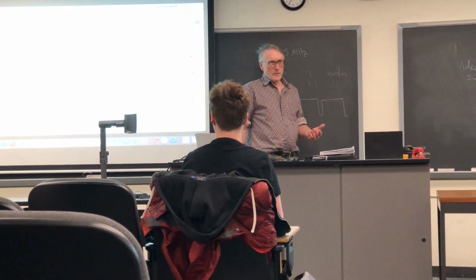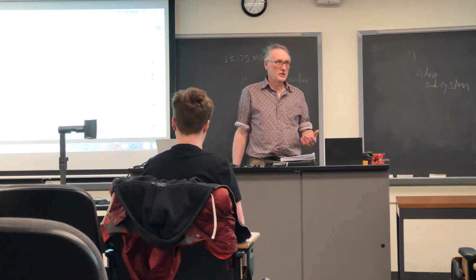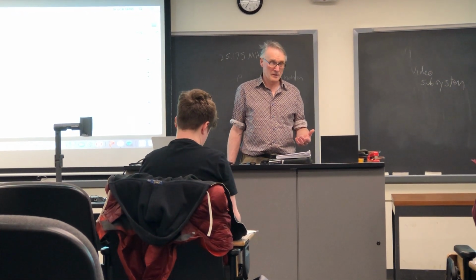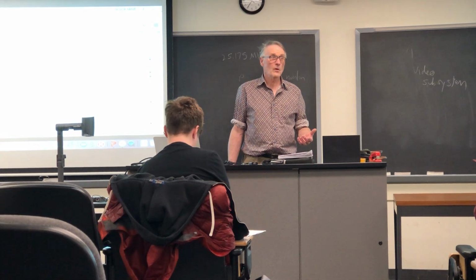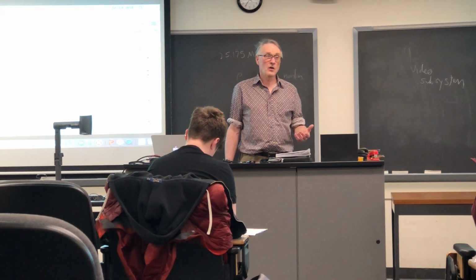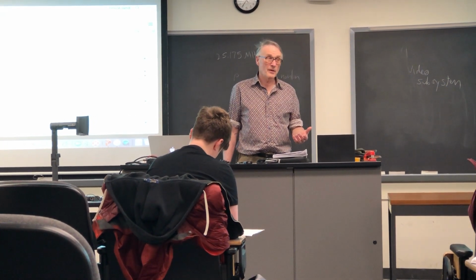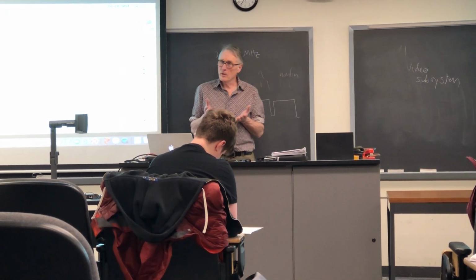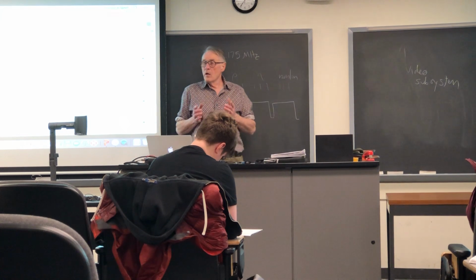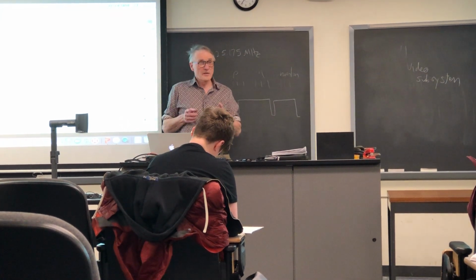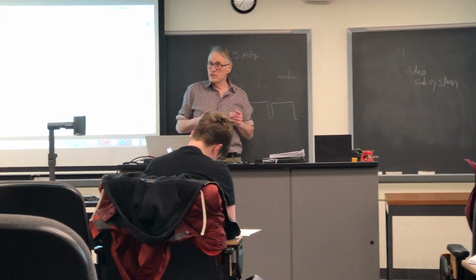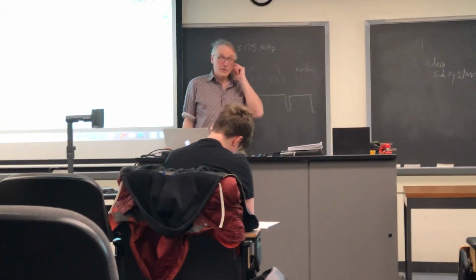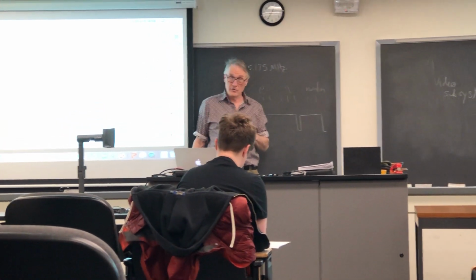One way to get around that is to break the VGA display into 20 pieces and have each solver write to its own carefully hoarded piece of memory. And then at 25 megahertz, that same memory is traversed by the VGA controller to grab colors back for a given VGA address.